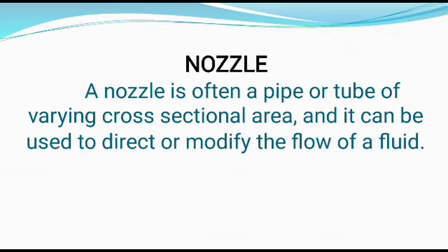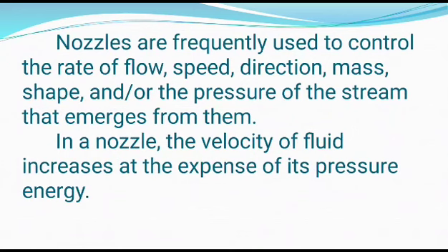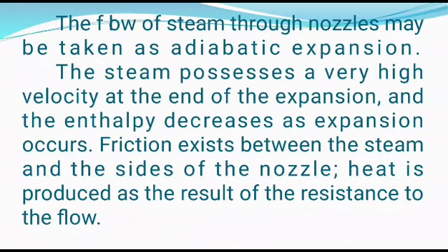or modify the flow of fluid. Nozzles are frequently used to control the rate of flow, speed, direction, mass, shape, and the pressure of the stream that emerges from them. In a nozzle, velocity of fluid increases at the expense of its pressure energy. The flow of steam through a nozzle may be taken as an adiabatic expansion.